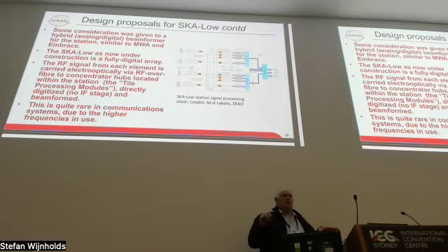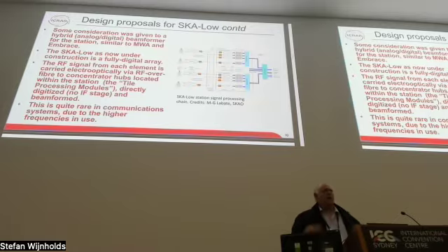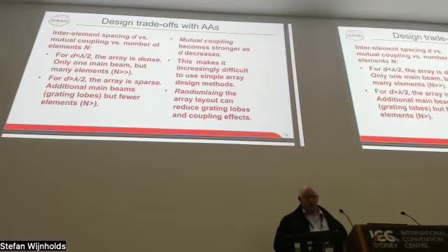I would also just quickly mention, although not directly relevant here, there was also a proposal to use a hybrid beamforming type approach, similar to what's used in LOFAR and also the MWA. The idea was to have the first stage being analog and the second stage digital. The issue with that is that you can only form one beam at a time, and like the EMBRACE system, which actually was multi-beam at a slightly higher frequency, it had to have duplicate analog electronics. I won't comment on this. Digital design is not my real field of research, but the fact that the SKA has gone for this all-digital approach does mean that it's probably future-proof and it's probably a good idea despite the extra cost.